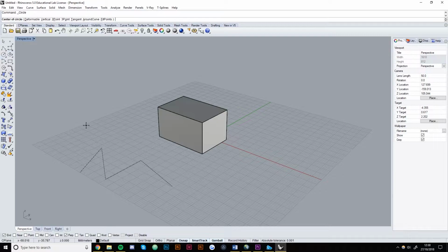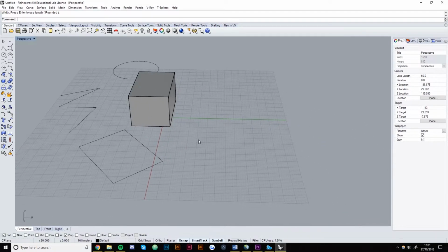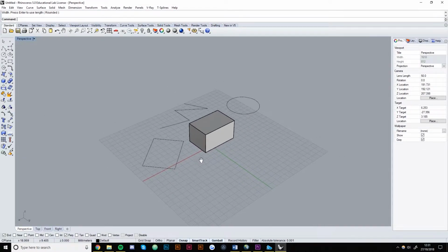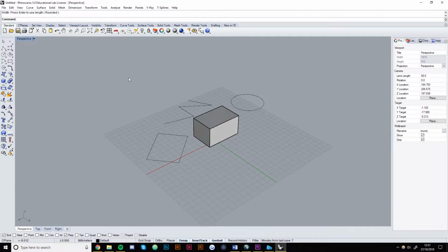We also have circles, rectangle tools, and you'll notice that there's these little triangles in the bottom right corner of each one. If you click on that, it's going to expand the view and show you a bunch of the different other ways you could draw a rectangle or something similar. So the default one here is the corner to corner rectangle, but you can also draw one using 3 points like this tool. So that would let you draw a rectangle this way. That can be super useful depending on what you're modeling or how you're trying to do it.